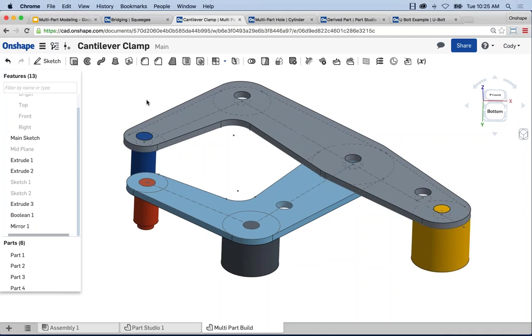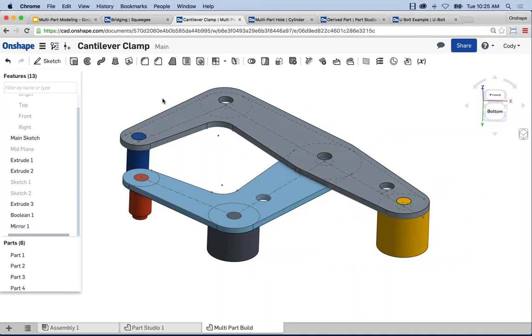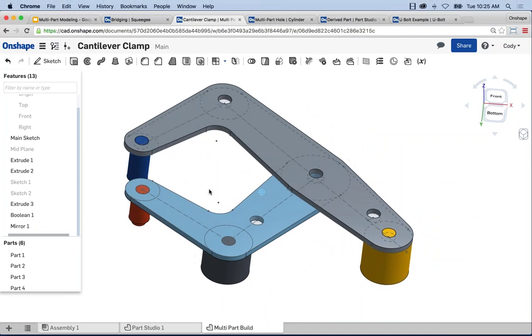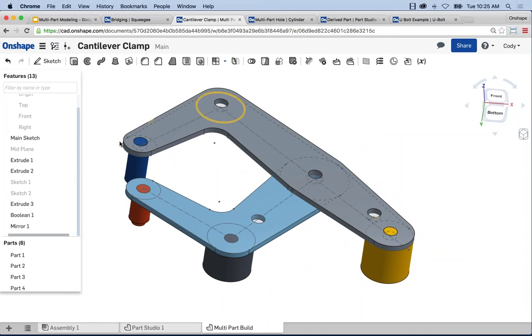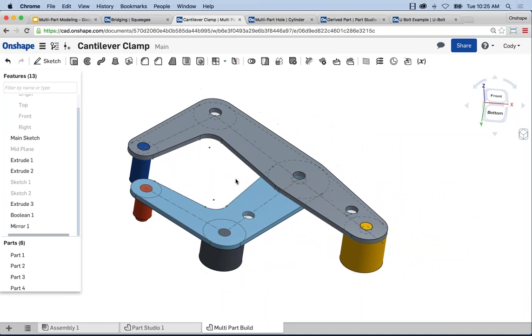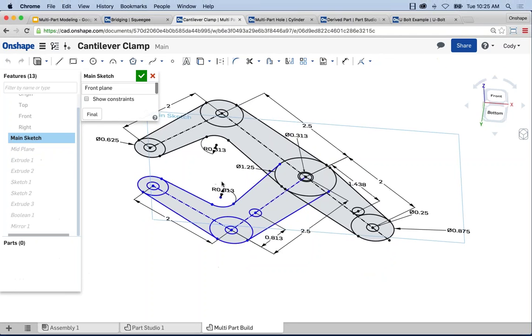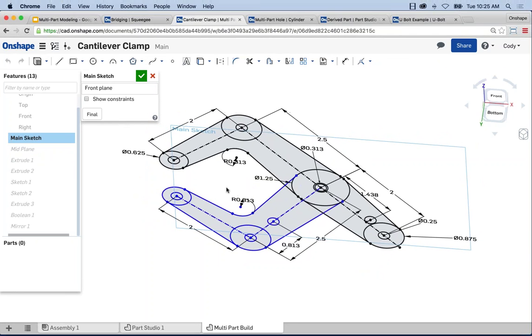All right, so that is the very first example that I have for building parts with contextual relationships. And the question may come up, well, why go through this effort? It is a little bit faster, and it certainly is. I didn't have to take a ton of dimensions to figure out where all these points go. But why would I bother with this? One of the biggest benefits of doing this is, as I mentioned before, one sketch really drives multiple parts.